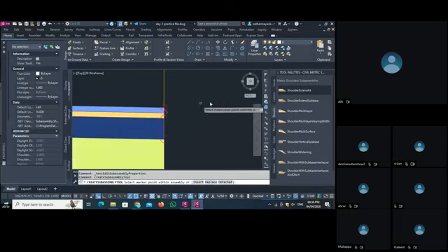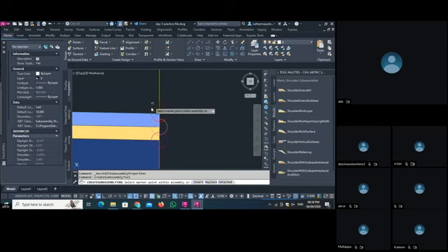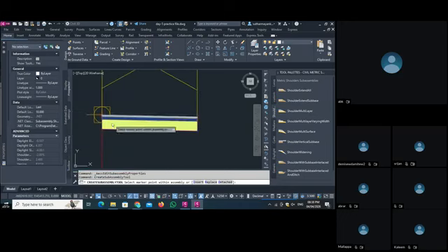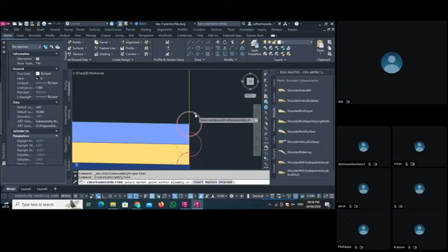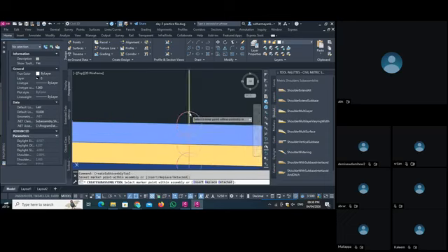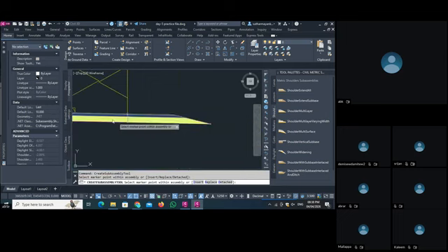If you want to add this shoulder here, you have to select on this top only. In this lane, on this round part, you have to click here. As you click on this round part, the shoulder itself attaches automatically with this lane. The same way, as we click on the shoulder, the properties of this shoulder are here.